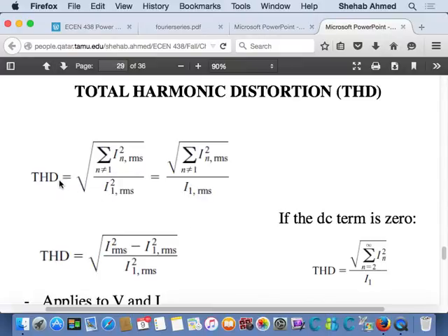So ideally, you would like THD to be what? What would you love THD to be? As a percentage. We typically calculate it and multiply by 100 and give it as a percentage. Yeah, you would love it to be 0. You would love THD, total harmonic distortion. It's distortion, right? You want to have distortion to be 0. It makes sense from the terminology, right? But if you look at the equation, yes, I want everything besides the fundamental to not be there. But it's there. You cannot have a pure sinusoidal waveform. There's no such thing as a pure sinusoid. So it will have some harmonic content, right?